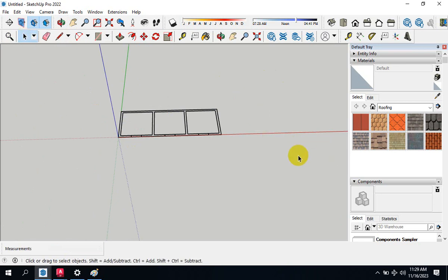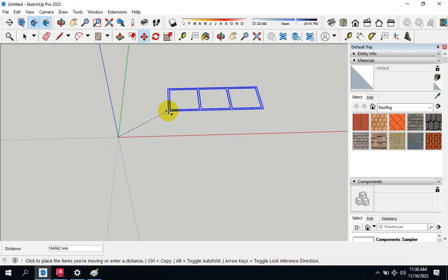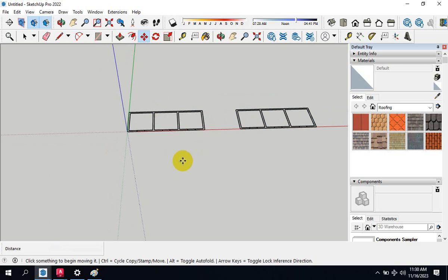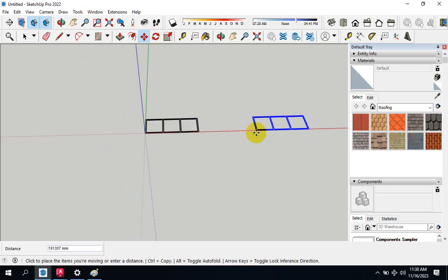Bai da wahala. If I highlight this whole drawing now for Amasali and I click on this one called move, I will hold on control, I will drag and I will release the control and I can drop this plan anywhere. So I have just copied this plan. So what if I don't hold on control Amasali and I click on this, now highlighting, I can move it. So you see one tool is doing two functions at the same time. So the second one, you have to hold on control to be able to copy.